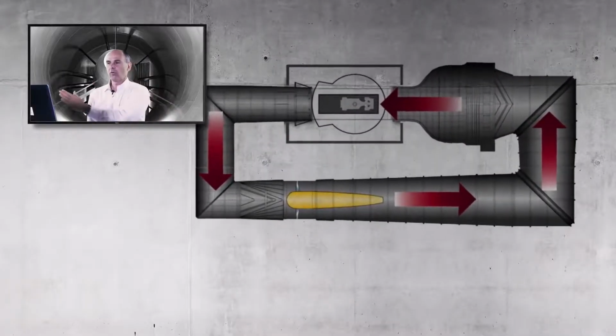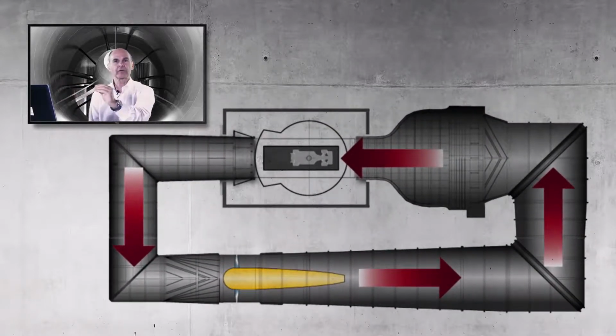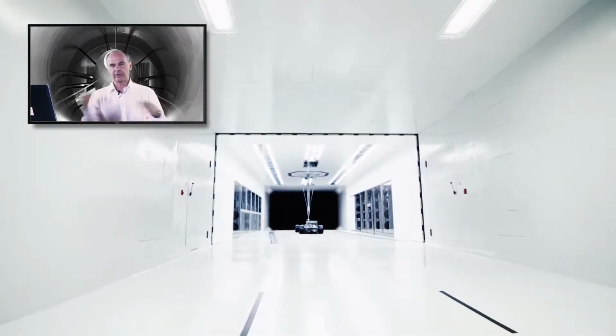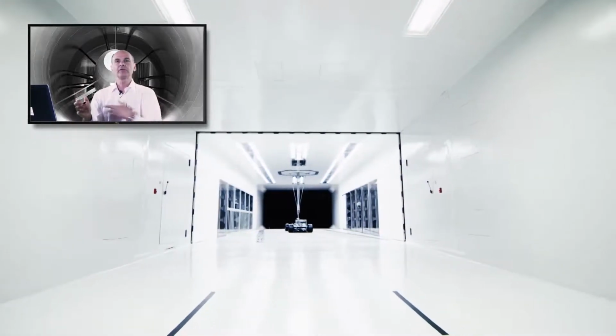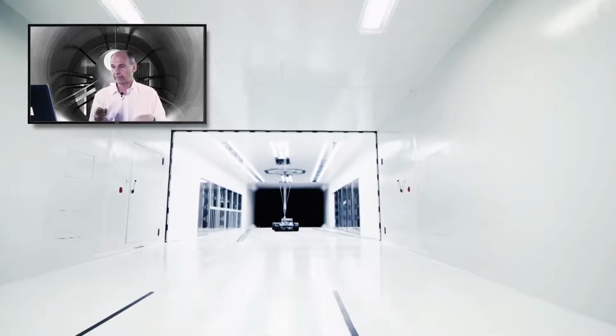We then also expand the air. You see the airline from the fan is expanding almost all the way to the working section, then it contracts for the working section, and after the working section it expands again. The main reason for that is the efficiency of the use of the air. It takes more energy if you kept the working section size all the same all the way around the airline, because then you have a higher build-up of boundary layer. The friction of the air on the walls of the wind tunnel is higher if the velocity is higher. And aerodynamic forces increase with the square of speed, so the friction is much higher at high speed. So if you gently slow the air down as you send it around the airline, you slightly reduce the losses you get as you send the air around your facility.